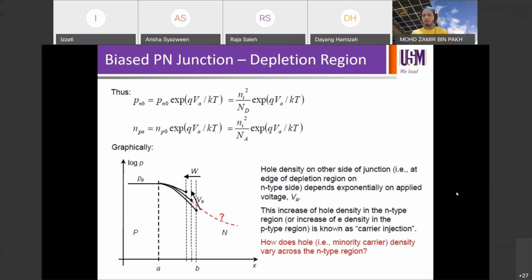And also we've discussed reverse bias, when we connect our p-type to the negative polarity and n-type to the positive polarity, opposite polarity, right? So we've discussed the change of barrier height under forward bias and reverse bias condition. We've seen that in forward bias condition, the carriers can continue to diffuse across the junction. And the moment they cross the junction, they immediately become minority carriers at the end of the opposite depletion region.